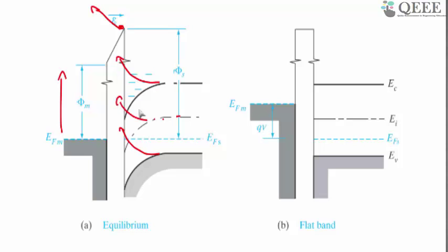But if I pull this down, the oxide point is pulled further down, and the conduction band also tries to go further down. So this is what the gate bias does. The gate modulates, or changes, the surface condition between the silicon dioxide and the silicon. So what happens when you change the surface condition? Keep in mind that the Fermi level is continuous.